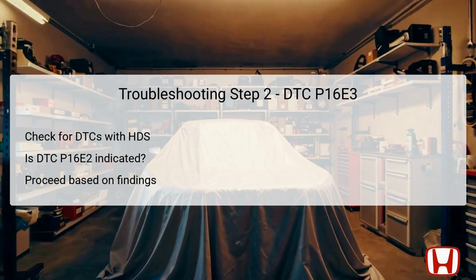Specifically, you need to verify if DTC P16E3, which refers to LIN communication errors involving the alternator control unit, appears. If P16E3 shows up as confirmed, it signals that the next diagnostic steps need to be taken for this DTC. Otherwise, if DTC P16E3 is not present, focus needs to shift to a deeper examination of other components involved. This check allows you to isolate the problem accurately and dictates the next troubleshooting action, either continuing with P16E3 or addressing any other issues present.